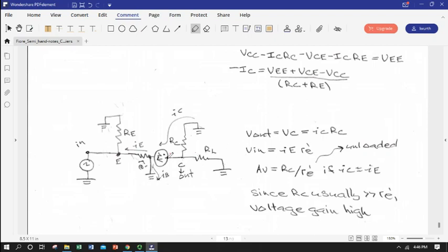So we know that current is going to flow in the direction of the arrow of the current source, so we know that we've got our collector current flowing in this direction from ground, dropping over this resistor, and it's going to continue to flow over our base emitter little resistor, our internal resistor, and then to ground through this resistor.